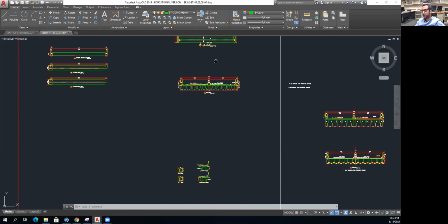Okay, and you also need to draw an elevation for your beam. So, for example, this is a typical beam elevation. As you can see here, we removed the thickness of our slab. So in our normal, if we did an offset, it's going to be like this. So this is the thickness of our slab, but here we are drawing our beam only. So I need the thickness of the flange and the depth of the web and the cross girders only. And with every drawing, you have to write its name, you have to write its scale and everything. Okay.